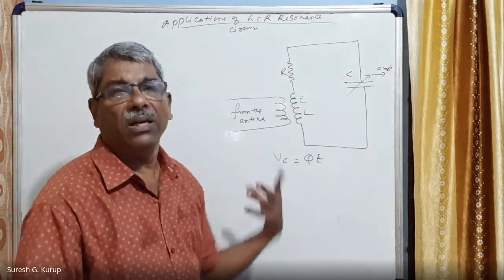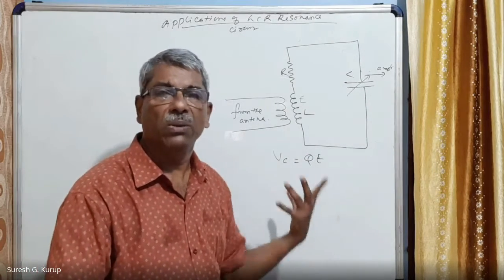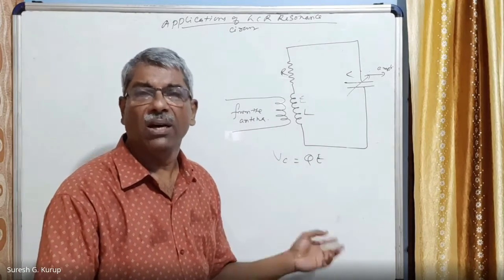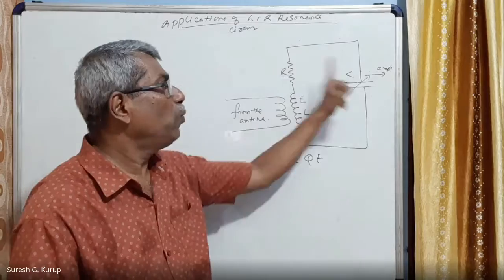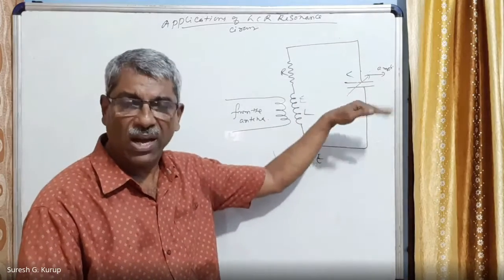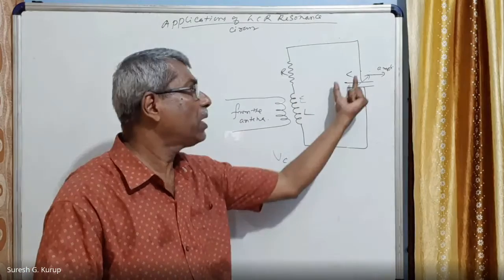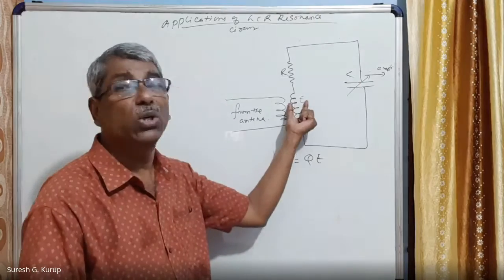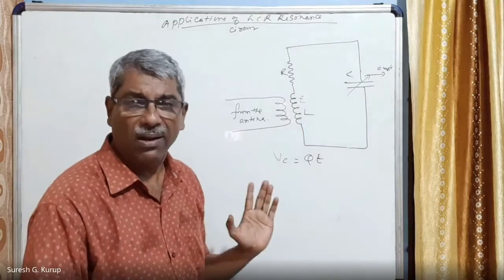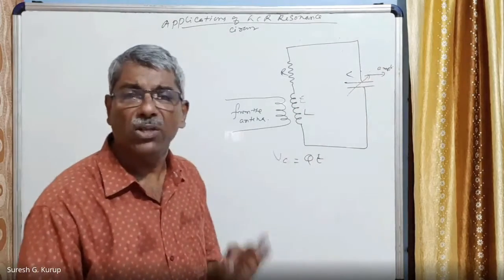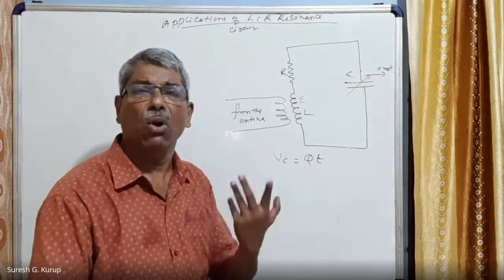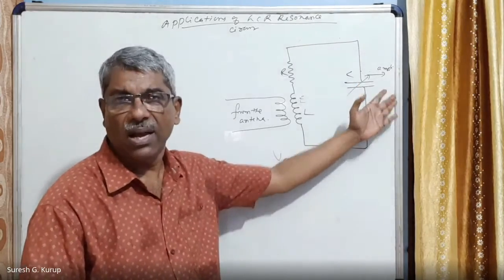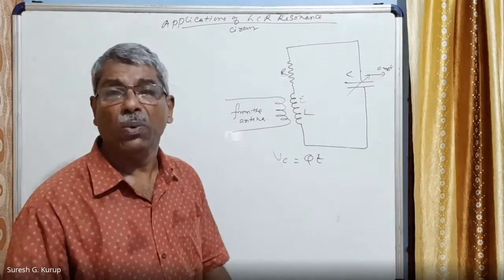That means XL becomes equal to XC, and the circuit becomes resonant. Hence the current becomes very high, and the voltage across the capacitor becomes very high, many times greater than the induced EMF in the coil L, right? So the amplifier gets a very strong, highly increased signal, and we can tune the programs in a proper way.